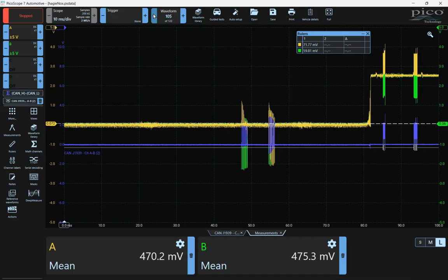So within the wire harness, there was the ground for the NOx sensors, and one of the pieces of copper out of that harness, out of that insulation, had over the years broken, and it pierced its way through the harness. This machine, I don't know, 5 years old probably, had actually pierced through the harness, and it's in a location where it's hot, right?